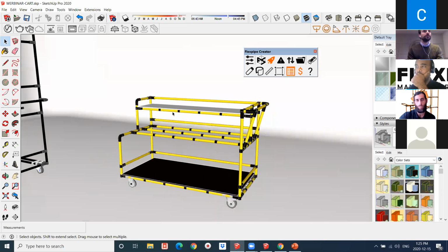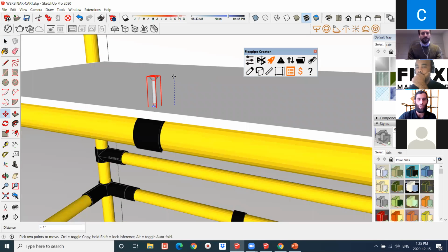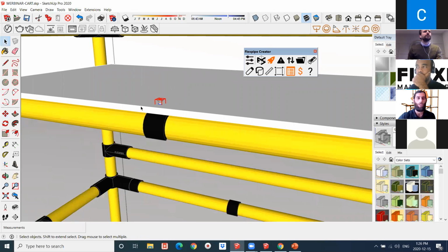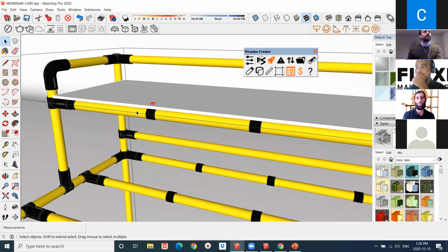So this is a good way to install them, like I mentioned before, right? We can install them from the top. And here we can see that we're using a screw to pierce through the surface, through the leveling shim here, and then also directly into the pipe, creating a strong contact point between the surface and the structure. And for those screws and the shims that you use to place surfaces along your structure, think of it divided into equal spaces. You can space them out at 12 inches, 24 inches, depending on the type of part that you will be transporting, okay?